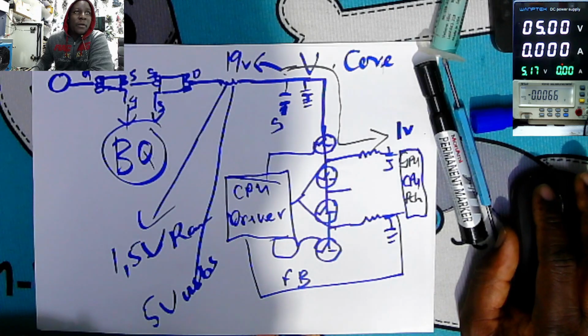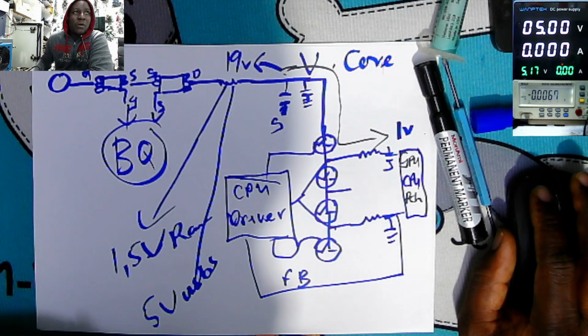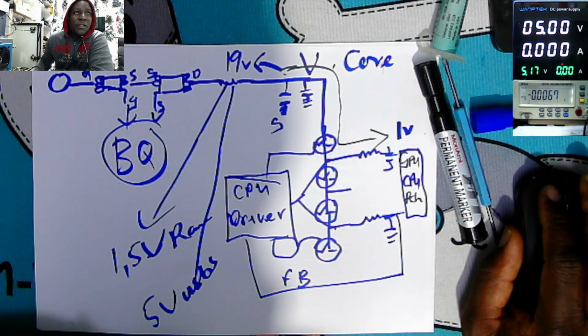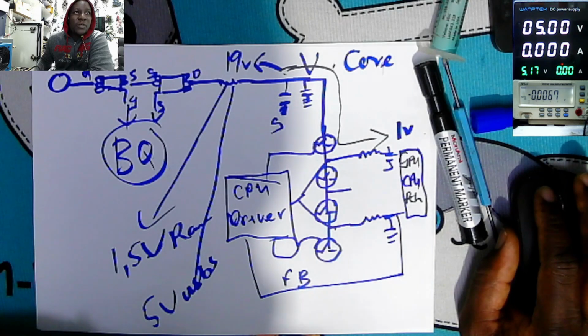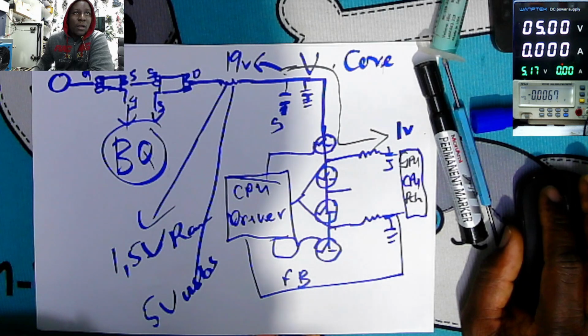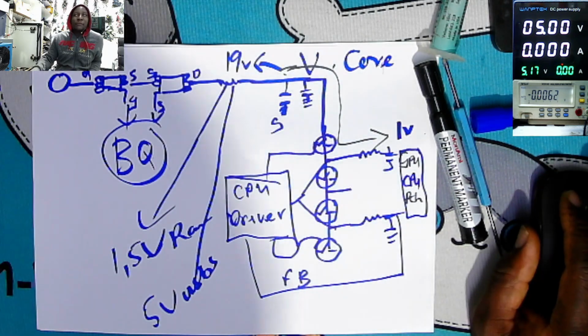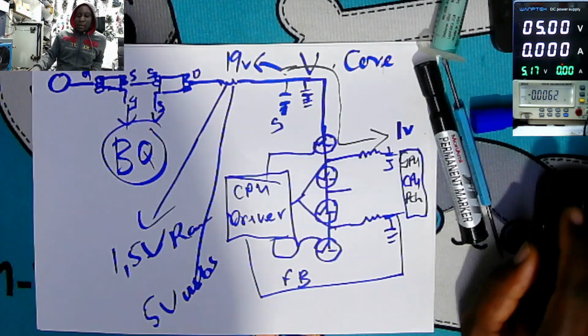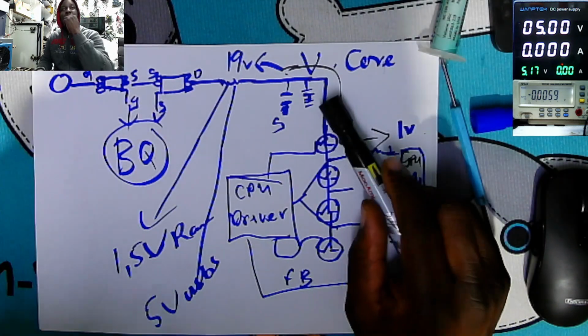Bra, can you help me? Same device, same problem. We have 3.3 and 5 volts on the power supply, but the coils on top of the chip have no voltage. BIOS and power key is 2.6, except the coil. 2.6 is not enough. If the, you know, the 3.3 and 5 volts regulator,